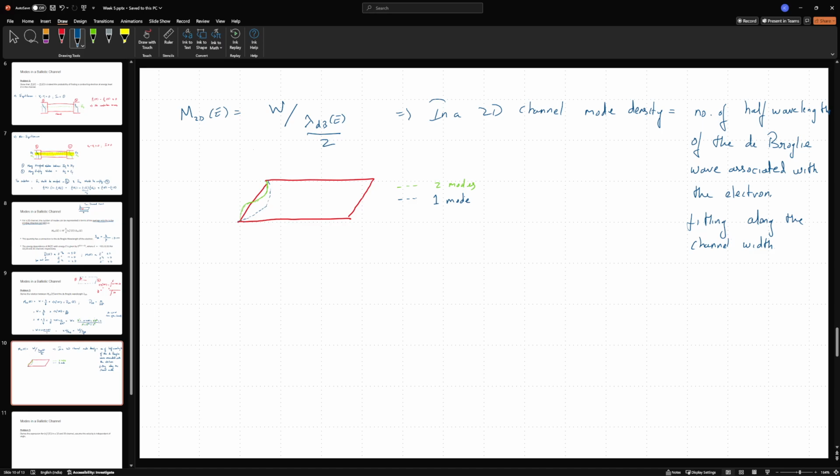So this tells us how the geometry influences the conduction. And this is something to be expected, because when we were solving quantum mechanics problems, we saw that the boundary conditions determined how the particle behaved. So this is not too different a situation from that. Here also we have a very confined geometry and very particular lengths and widths associated with the channel, and because of that, not all energy values of electrons will participate in conduction. Only certain select energy levels will participate in conduction, and even among those, the number of modes will determine how many electrons at that energy level can actually take part in conduction.